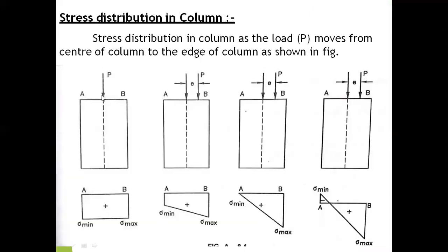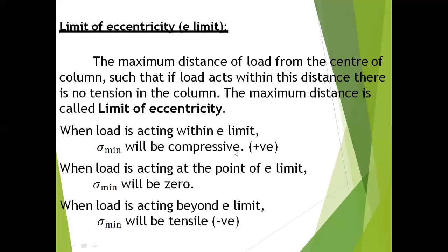So these three are very important. When the load is at the center, there will be no such stresses. When the load's eccentrical distance is within the limit, then only compressive stresses develop. When the eccentrical distance is beyond the limit, then tensile stresses will develop. Tensile stresses will make the member have a reversal of stresses. So these concepts are very important before proceeding into the problems, before proceeding into how real application structures are subjected to direct and bending stresses. I hope you all have understood the concept I have explained so far.